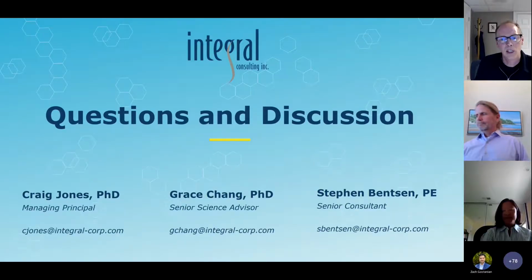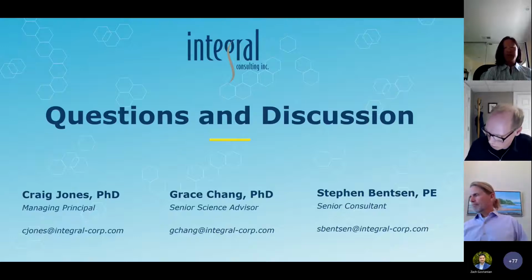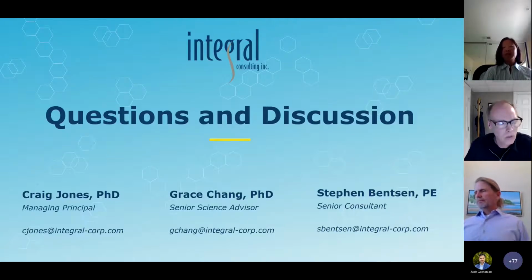And then Grace, with the optic system, what constituents can actually be monitored with that system itself? Yep, so it's mostly hydrophobic chemicals. We have demonstrated it for, in addition to the PCBs, mercury, methylmercury. I mentioned copper and lead, DDT, dioxin. The one limitation we have found to date have been PAHs.